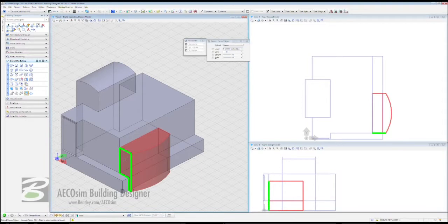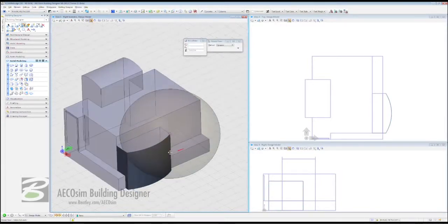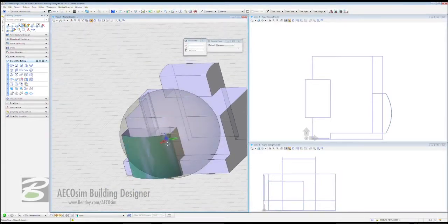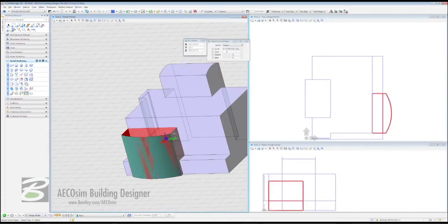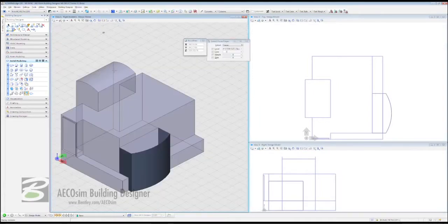Select it twice to say that is, and three times to say to accept the extraction. Again, the front, and here we're going to come up to the top, click on View Rotate, and we're going to move around here so we see that other face. Just right click to reset. I'm going to say accept that.